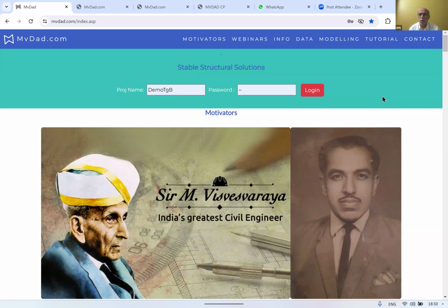I have put the most efforts to make this earthquake resistant. If our structure is resistant for the earthquake, that is roughly, as you have seen, 3% to 4% of the total weight. What I observed from my experience, for wind load, it comes around 1 to 2%. Not more than that. So automatically our structure is safe during the wind condition also.